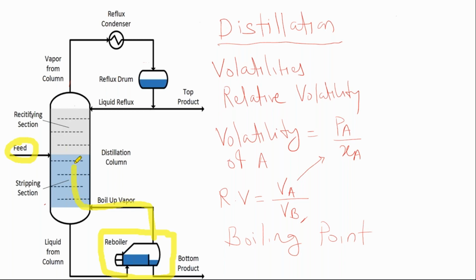So all these vapors or vapor particles, mostly benzene and lesser toluene, are going towards the condenser, where these benzene vapors or benzene-rich vapors are going to condense. It means the vapors are going to convert into liquid phase with the help of phase change techniques. That is, the latent heat is going to be removed or absorbed by the condensing liquids.